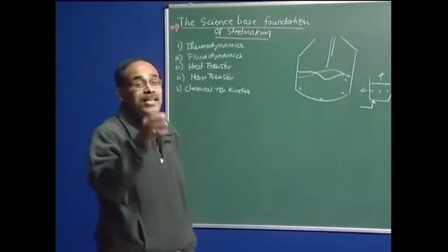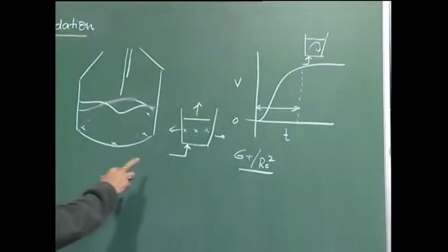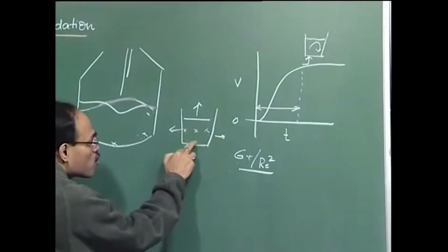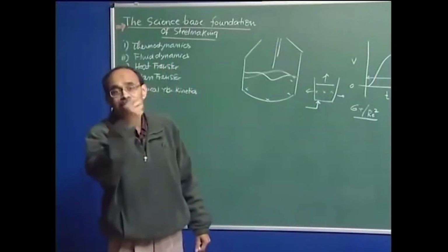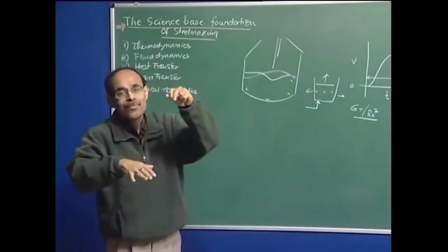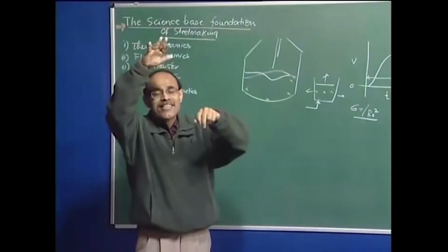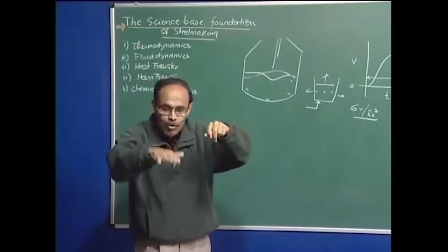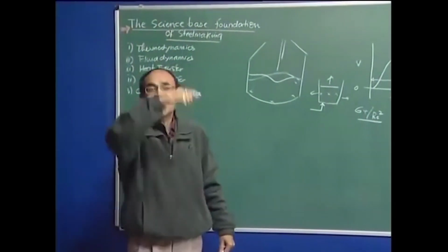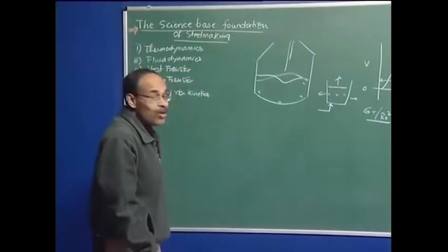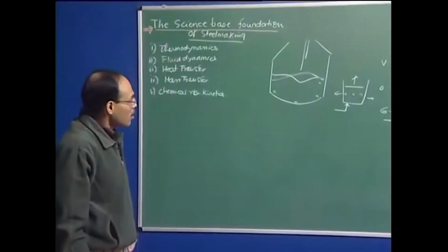So, in some systems where we have no strong forced convection current, the non-isothermality can affect our fluid flow, because difference in temperature will cause difference in density. Heavier density fluid will go down, lighter density fluid will go up, and that creates a natural convection current under the influence of gravity, which is called natural convection or thermal buoyancy.